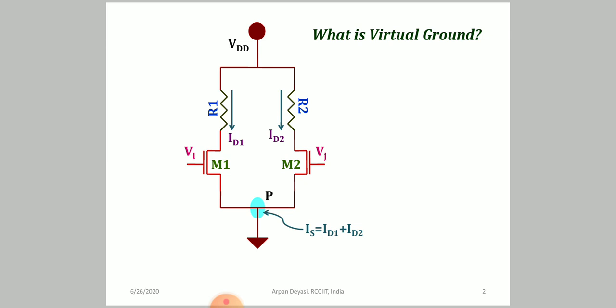If you go to the circuit I have drawn here, you will find that the major part is nothing but a differential amplifier. One significant point is that this differential amplifier is not made of BJTs, as you will be familiar with in most of the cases in the exercise book. This differential amplifier is made by MOSFETs, two N-channel MOSFETs.